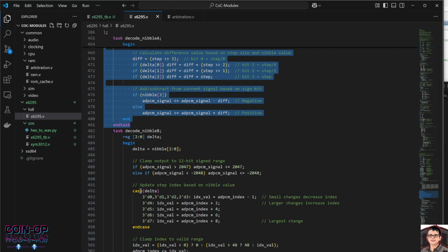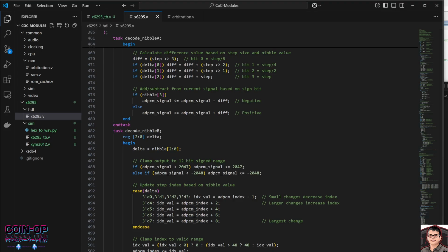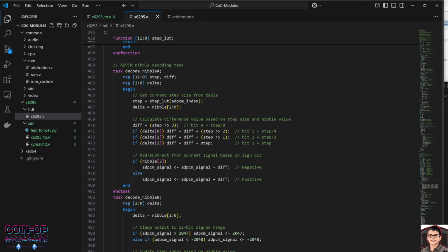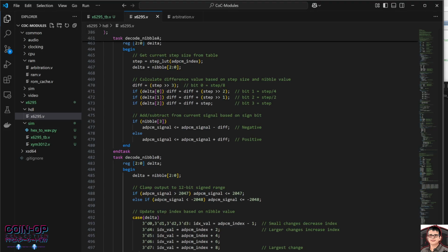Okay, so these are the decoding stuff, and I split it into two different parts because some of these have multiplication and all that stuff. You ought to be very sensitive about lots of different addition operations chained together in combinational form. A lot of this is combinational, and multiplication in FPGA could blow up your timings, right?